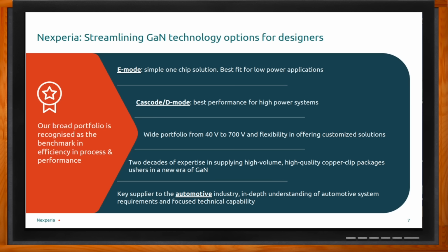The Cascode is a very advanced approach to how the GaN is being packaged. The key to the Cascode FETs and our package at this point is what we call a CC pack. And the main reason for the CC pack being what that is and why I like that: internally, there's nothing but clips, or as we, the older generation, call it, bus bars. Most of the packages, internal packages, even for the newer GaN applications from the bigger companies, I'm not naming names, have what we call bonded wires.